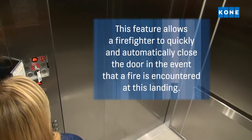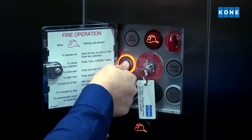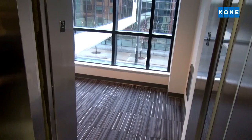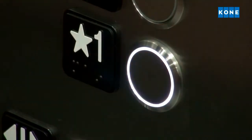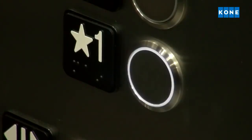This feature allows a firefighter to quickly and automatically close the door in the event that a fire is encountered at this landing. At the firefighter's panel, press and hold the Open button. Release the button when the elevator doors are fully open. The doors should remain open. Place a car call for another floor. At the firefighter's panel, press the Call Cancel button. The car call should cancel.